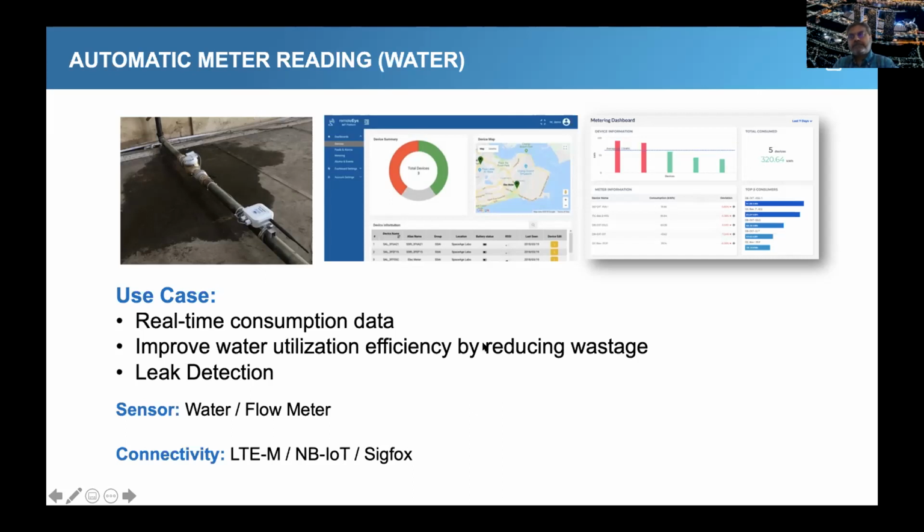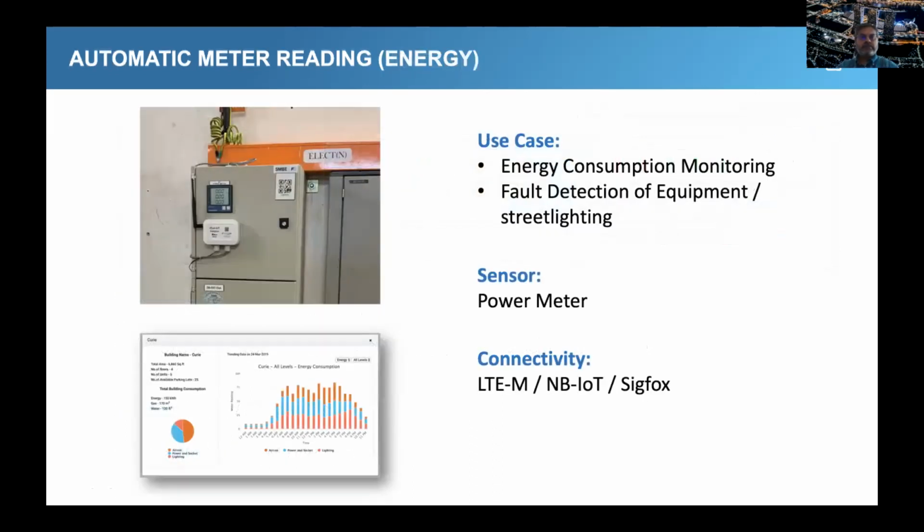So it simplifies them. They no longer have to do manual data collection analysis, and this can be submitted for regulatory purposes as well. Now, similarly, the same device can be used to connect to an energy meter and get data from that. So depending on the use case, you might monitor energy, current, voltage, power quality, XYZ.